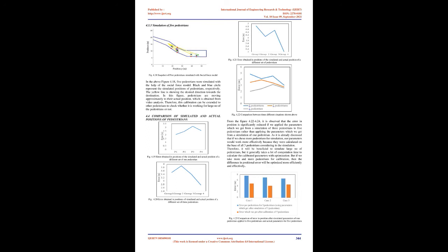From figure 4.12, the relationship between pedestrian speed and flow is defined. These curves, comparable to car flow curves, indicate that there is space available to choose greater walking speeds when there are few pedestrians on a path, i.e., at low flow levels. But as the interactions between pedestrians became stronger, the speed started decreasing as flow rises.